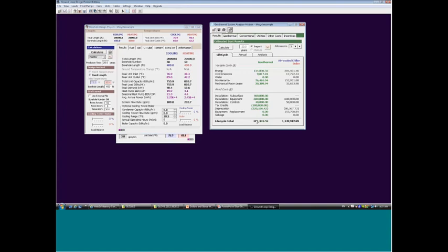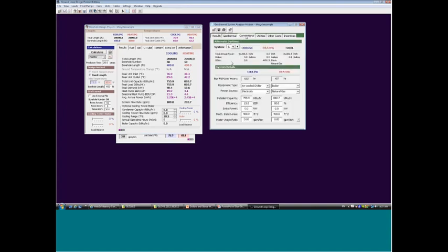But Adam's question was a little different. There's an alternate button in the GSA at the top right. What's its function? Okay, good question. On the conventional tab, we can define multiple different conventional systems. For example, system 1 here is an air-cooled chiller, electric, and boiler, natural gas. I could define a system 2. Like I can make it a very high efficiency air-cooled chiller. I could make it a very high efficiency natural gas boiler. And then I could basically have my mechanical room area here.